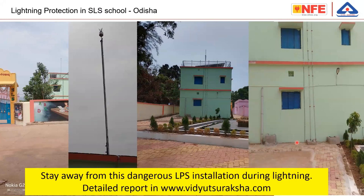I also request the participants, please note that such dangerous installations shall not be done in a school. Small children are going to play sometimes in this area, and no one can control children and tell them you have to be inside the building. This is the boys' hostel in a school. Imagine during the afternoon, on a Sunday, no teachers are there, and children are playing outside near this down conductor and there is a lightning strike. Then they are in deep trouble. So such installations shall not be made.